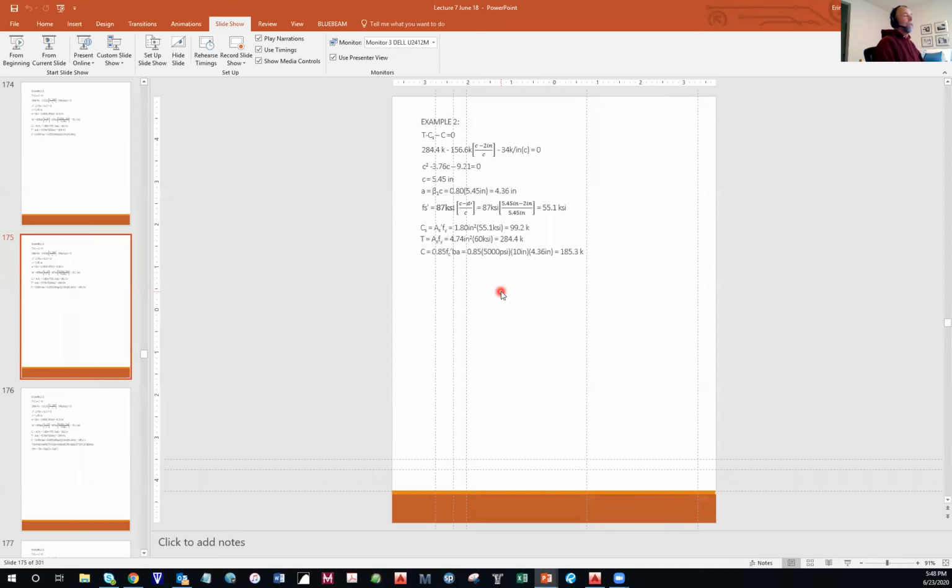That's how it goes. For your design, your designs follow like what we did on example number 3, where you have this load that you have to be able to carry. If you're able to carry it with just flexural steel, then you would just carry it with flexural steel. You don't need to bother with compression steel.